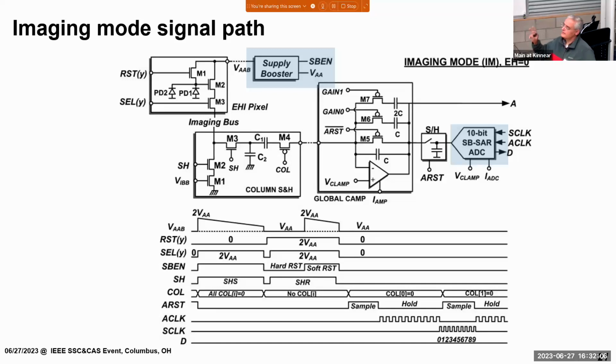Yeah, the thing is, this is a C5, 0.5 micron technology. This is a FOX process. It's not an STI process. If it's an STI, then you can talk about the leakage on the STI, but this doesn't have an STI. That's why we stick with this, because it has low leakage, even on the photodiode side. Some other people tried to build energy harvesting pixel technologies. They couldn't, because they are not really careful about where the current is going, or where leakage is happening. If you try to use 180 nanometer with STI, try to do this, it's good luck.